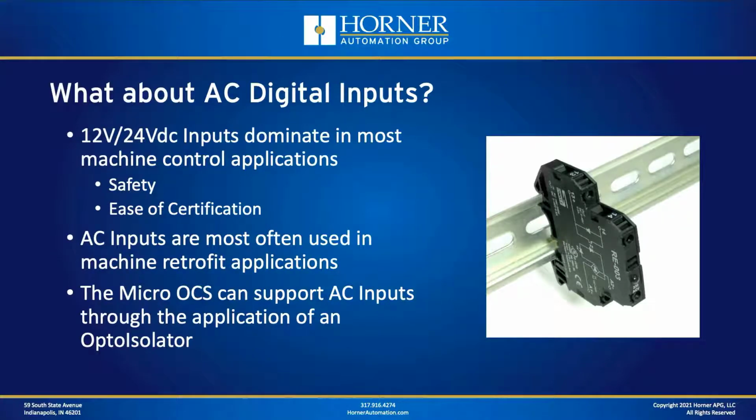But when you do have AC inputs, you're most often going to find those on machine retrofit applications. Maybe a machine that's older and you want to upgrade the controls, but you're trying to minimize how much of the I/O has to be swapped out. Or maybe it's just an application where there are some AC signals that you want to sense. So there is a good reason to do it from time to time.